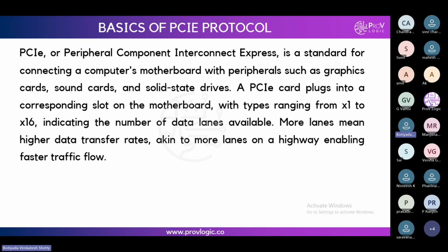It acts as a mediator between the processor and the endpoint. Processor means our host, like the computer giving instructions through the processor. And endpoints are either graphics cards, USB ports, sound cards, or Ethernet and so on. These are the endpoints. The mediator is PCIe.